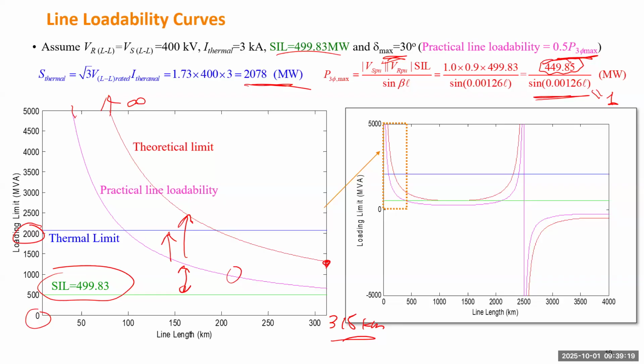Okay, does this make sense? Any questions? All right, so this is half, and this point is a quarter of the wavelength. You need to expect to have a line shorter than, at least shorter than, a quarter of a wavelength. That's already very long, already longer than 1,000 kilometers. So in the real world, it's not a very practical length of line.